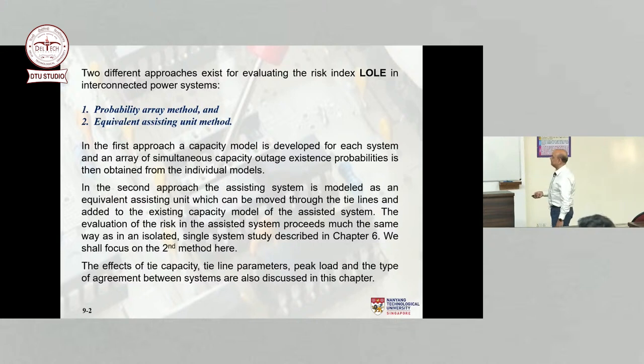That's what will happen. So in the first approach, a capacity model is developed for each system, and an array of simultaneous capacity outage probabilities is then obtained from the individual models. I'm going to deal with only the second method.